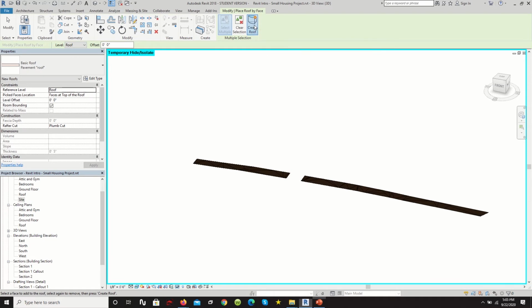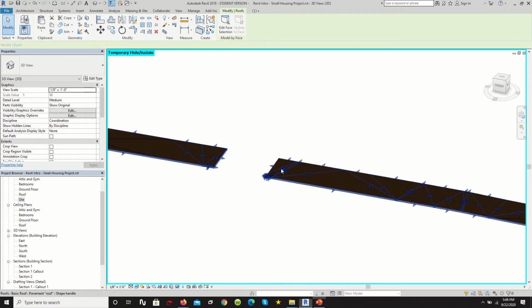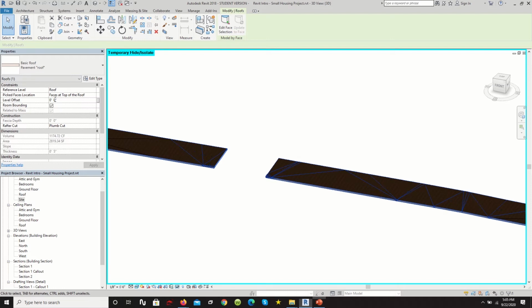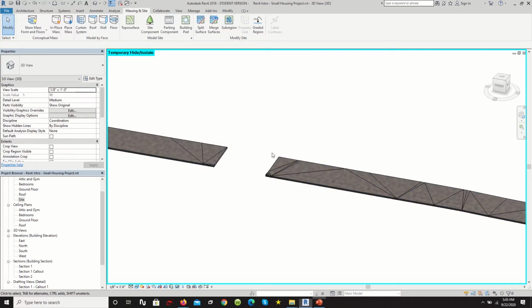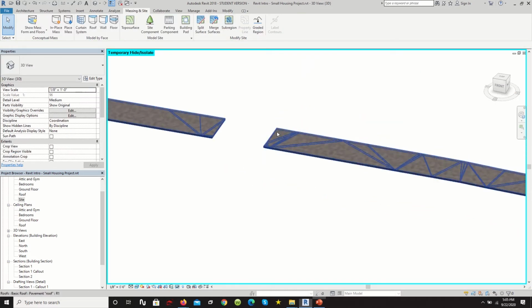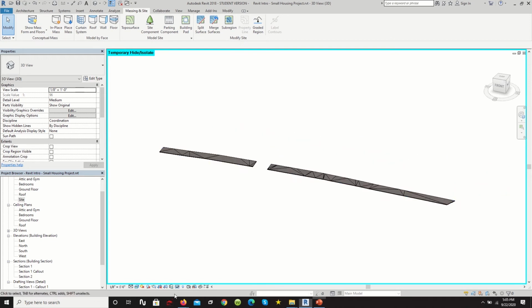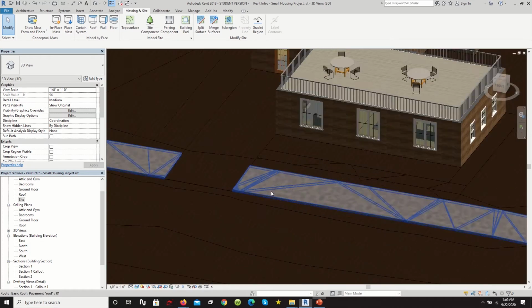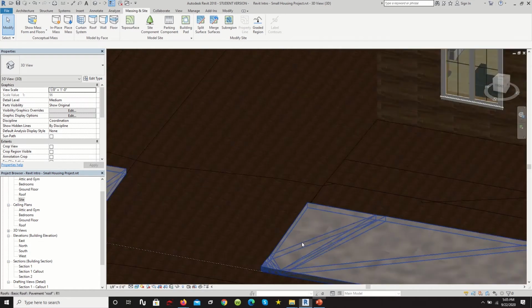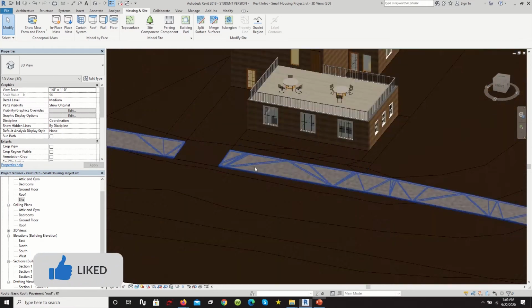And after that, we just had to hit create roof. So once we finish, we could click on the object. Let's level offset maybe 5 inches. And now when we turn off the hide isolate, now we have our pavement and the appropriate thickness for our pavement.